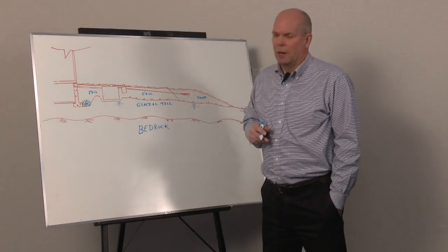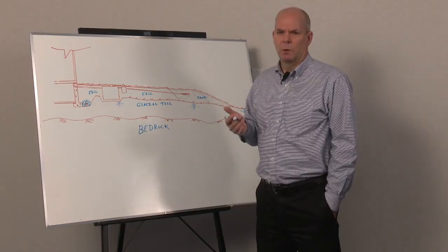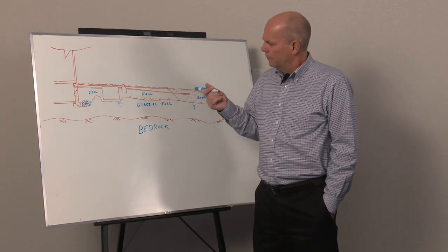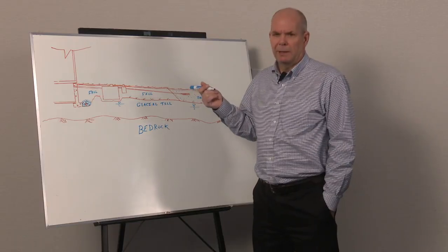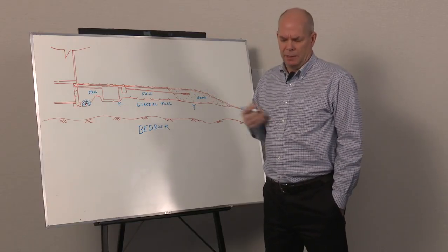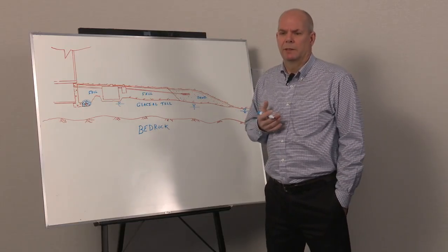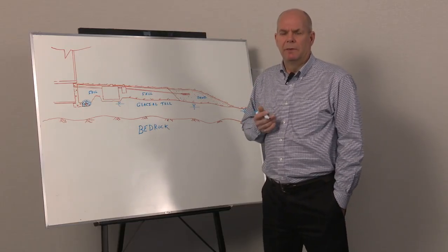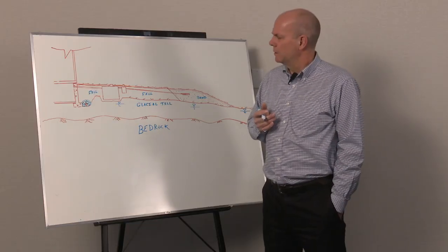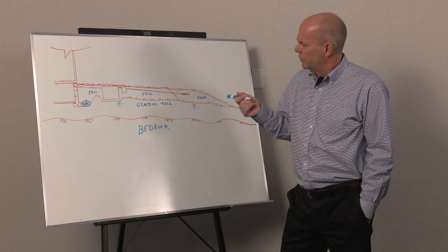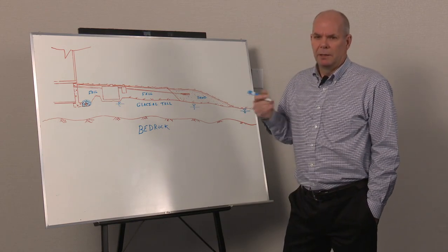Fill, if not placed properly, can settle under its own weight for several years, and usually when you take a clay-based till and use it as a fill without proper compaction, the clays can behave in a variety of ways, and it's based on the moisture content at the time.